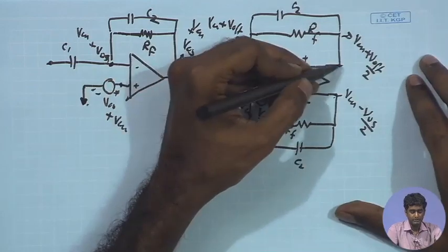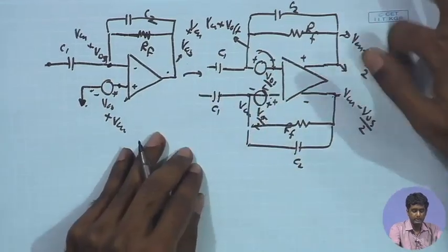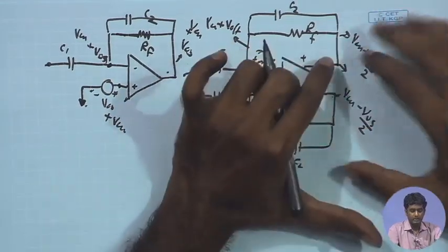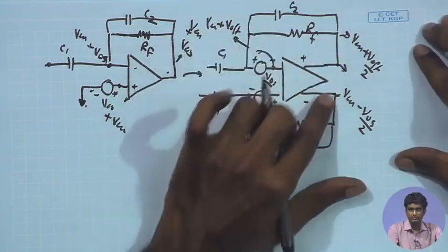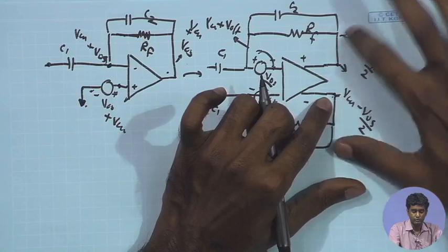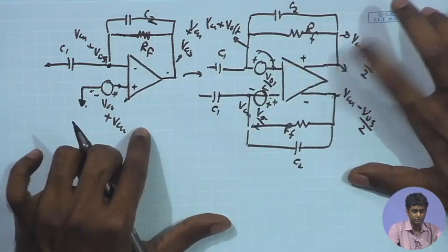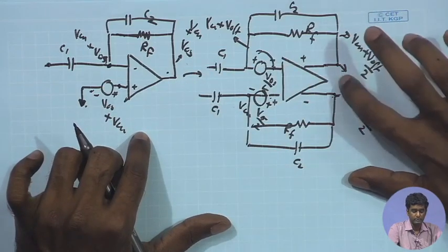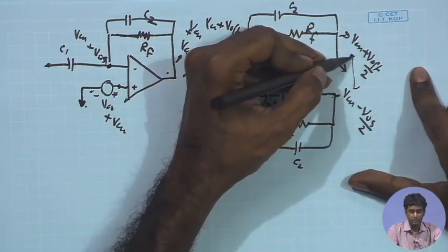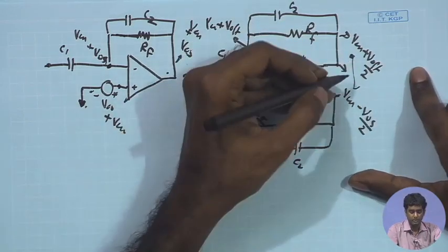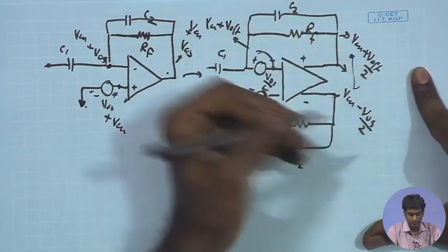the output DC potentials will once again be set. The common mode feedback will force the output DC potentials to remain close to VCM, and therefore it will try to push them to VCM plus V offset by 2 and VCM minus V offset by 2. Therefore, the difference between the outputs will not be much larger than the V offset.